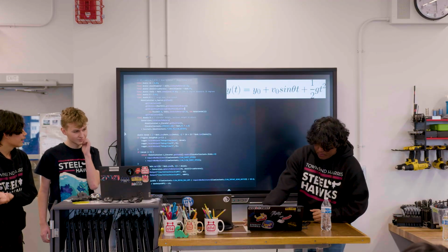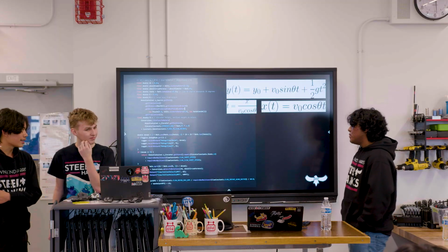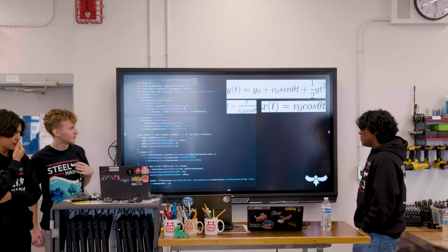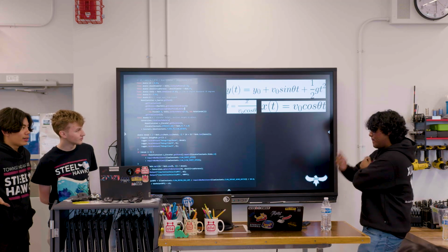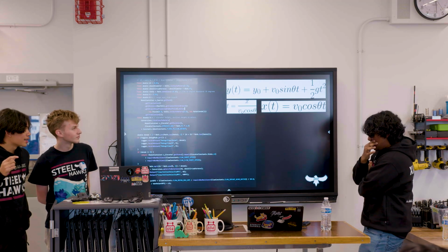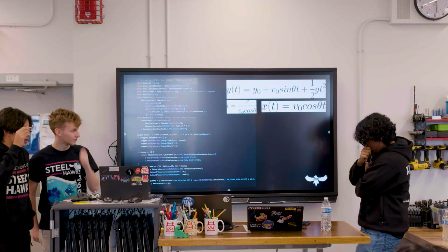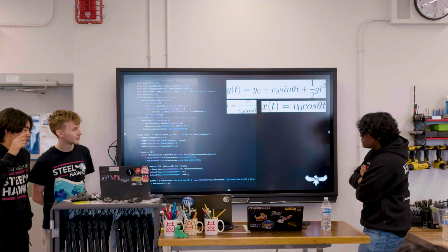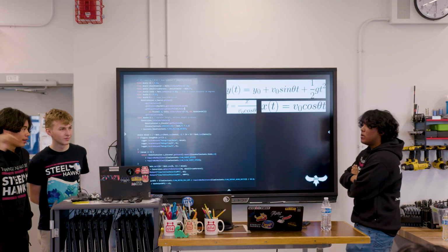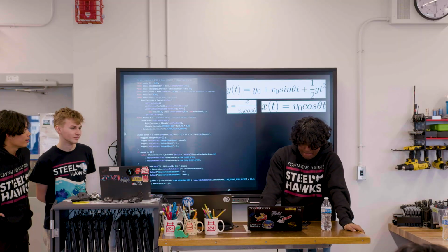So our next step is to find time in terms of constants that we know or that we're going to solve for. We use the equation velocity equals distance over time, and rearrange it to solve for time. Time is equal to the distance the robot is from the reef divided by the horizontal component of the initial velocity that we're going to give to the coral.